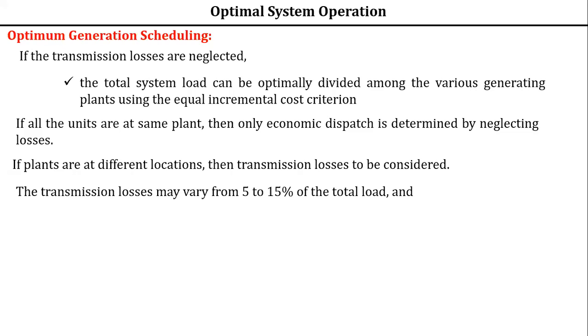What is the generation on the generator side? Anyone? What is the generation to be? Load is 100 megawatt. You assume that there will be a loss of 10 megawatt. Transmission loss is 10 megawatt. So then what will be the generation to be?